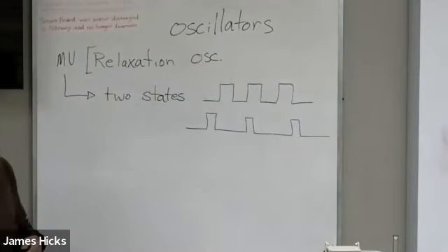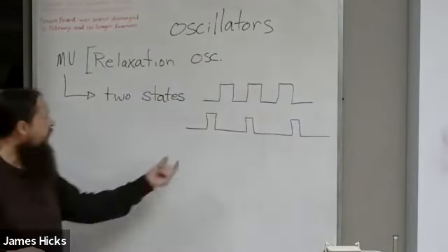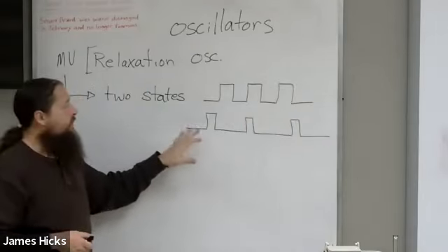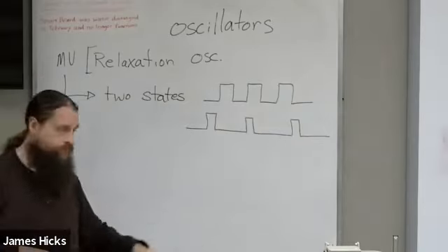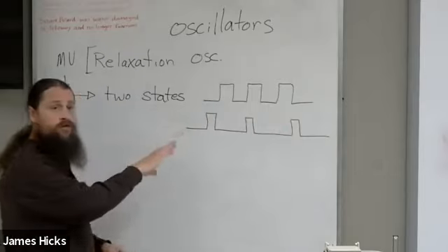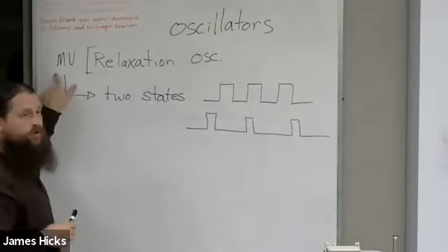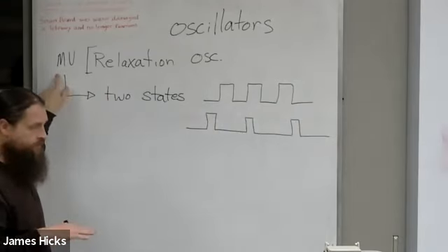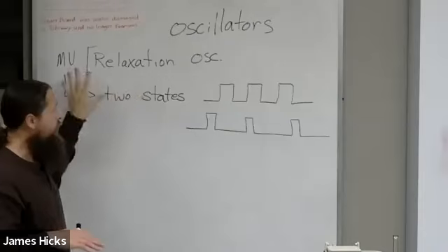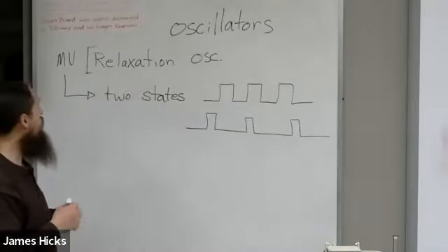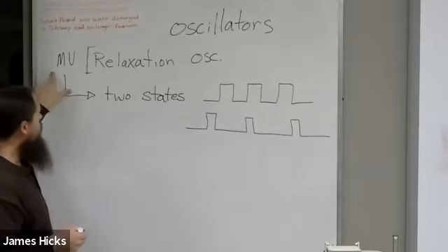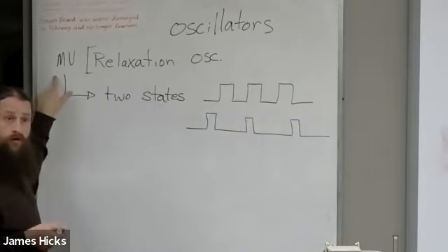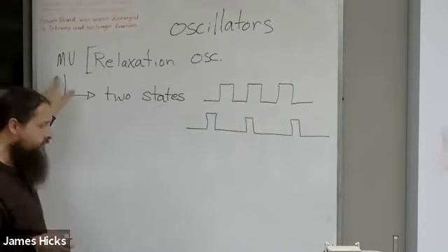You could definitely change the duty cycle of the pulses, like it's on less than it is off. But you're stuck with the square wave. Not that those aren't useful. There's a whole lot of stuff that multivibrators are crazy useful for, and they're not something that one ignores. It's just a very useful general tool. And one thing that we'll talk about on Wednesday is a simplified way to build multivibrators using a single integrated circuit.